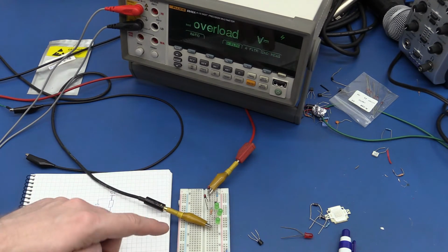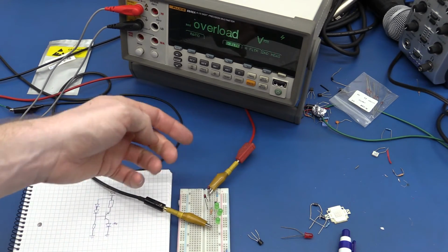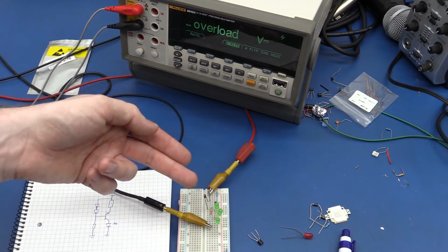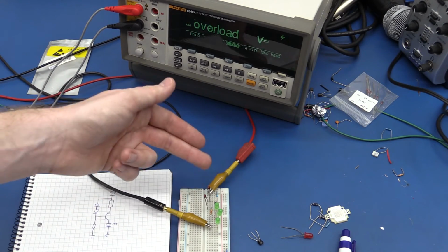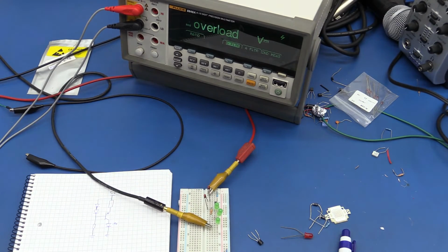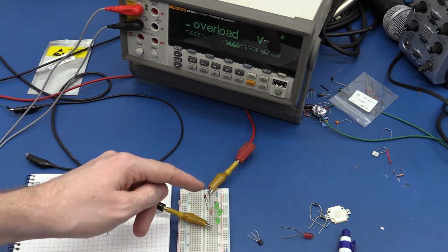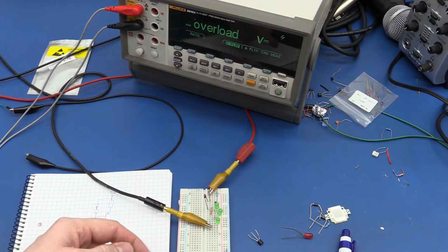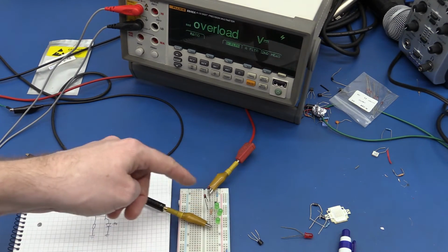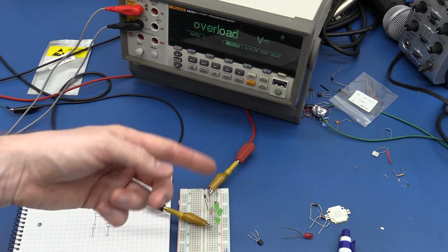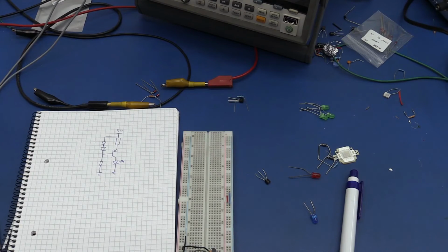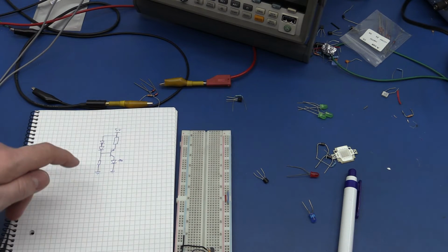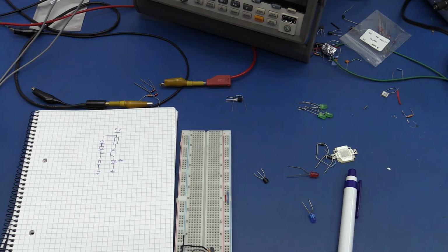But again, it's not always that you can select the supply voltage yourself. If the rest of your system runs on 12 volts, well, then you kind of normally just use 12 volts to drive your LEDs also. And with a normal current limiting resistor, you get down to 5–10% efficiency. And in that situation, this circuit will not save you. It will be the same efficiency. And so that's when we get into the switch mode converters. But first let's take a look at some more linear ones.